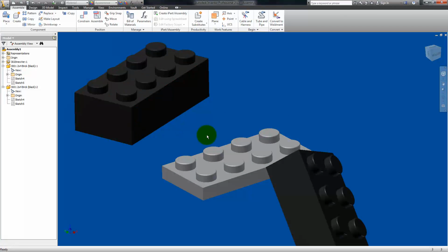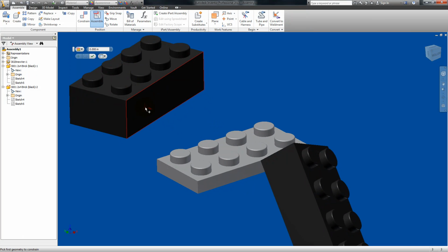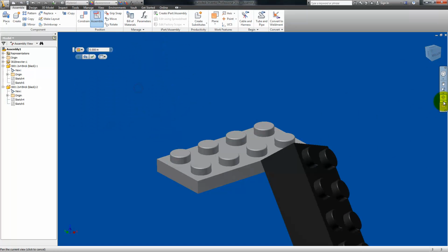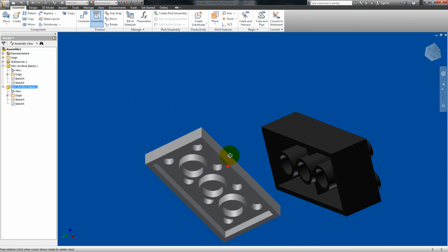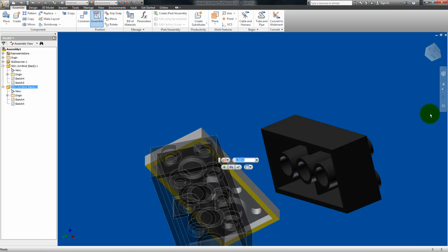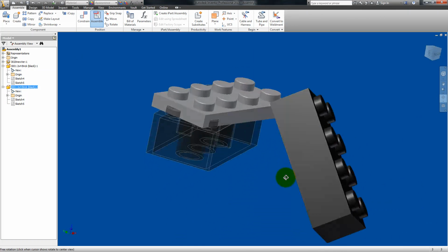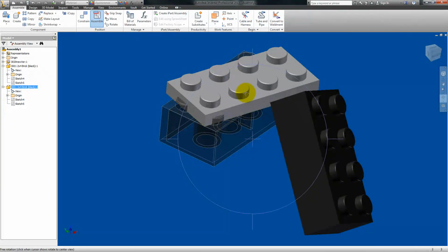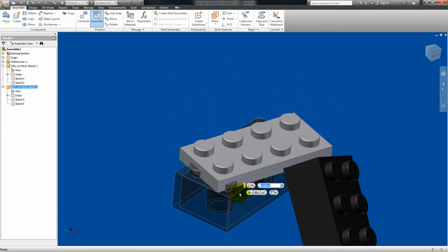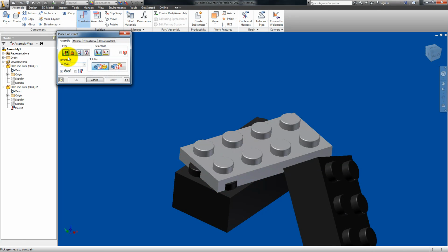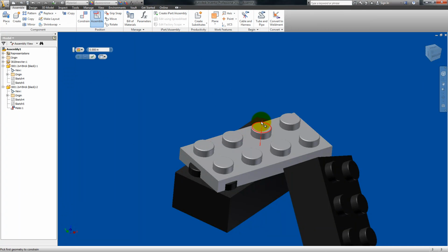So instead of having to click through each constraint, you could just click assemble, and then you can mate this with this. It's just a quick way to do the stuff that I showed you. And then maybe, oh, then you enter, then it prompts you for a distance. So we can say, if we want to say 10 or 1, it's basically an offset. But a mate offset 0 is touching. We have that option in the constraint as well, offset here, but usually you keep it to 0. So we can click assemble again and align